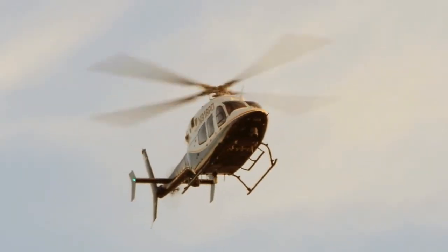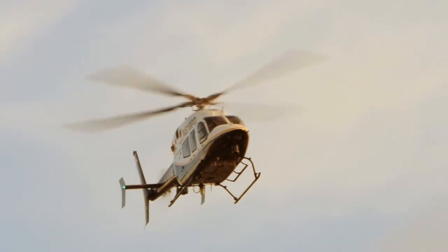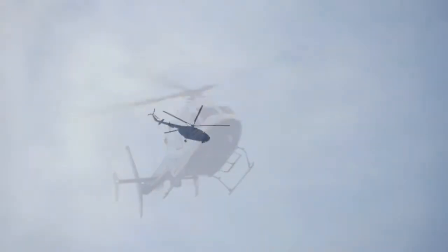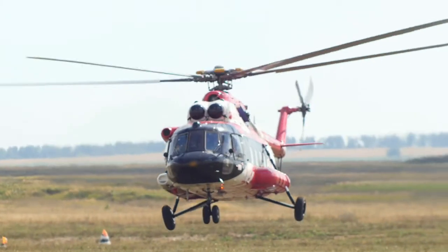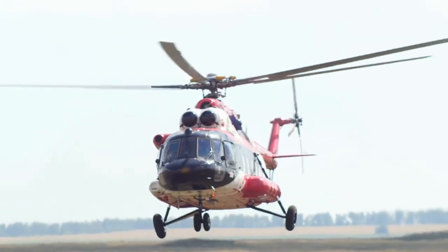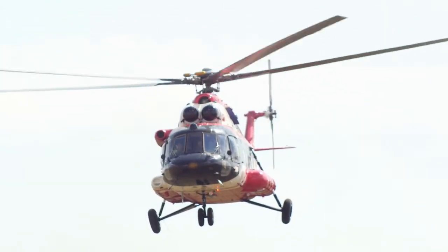It turns out they do have parts that act like airfoils. They're rotor blades. Unlike an airplane, helicopters don't have to travel down a runway to reach the necessary speed for takeoff. These machines spin their rotor blades through the air, pushing air down to generate the same pressure imbalance we see with fixed-wing aircraft. The pilots speed up the main rotor and set the blades to the proper angle to generate enough lift for takeoff.